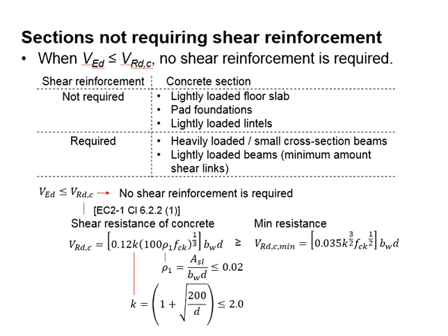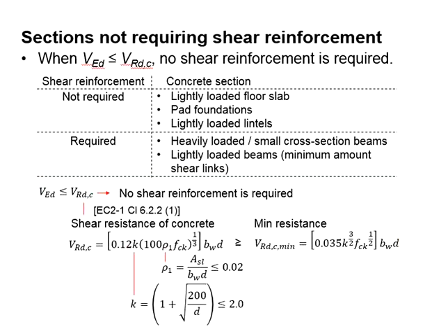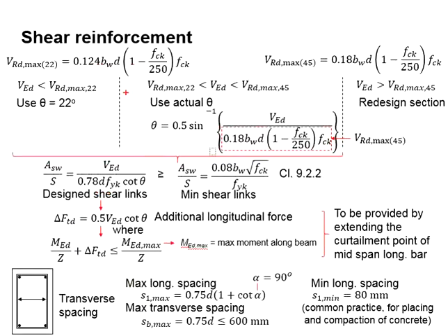To make it simple, if you are talking about large elements such as slab, footing, staircase, etc., relative to the shear loads acting onto the member, the section is relatively large. Most likely shear reinforcement shall not be required. Therefore, you will use this set of equations to check. As for small members such as beams, then you use this set of equations.